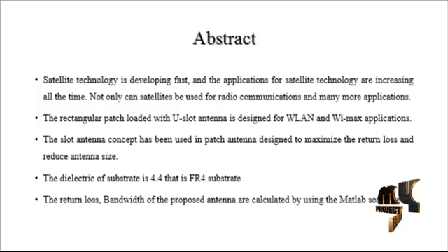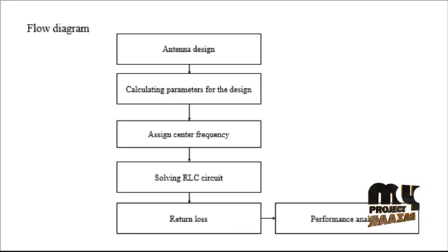CMA is carried out for critical parameters such as substrate electrical thickness, slot width, probe radius, and feed location variance to assess the dominant effects on the characteristics of the U-slot microstrip patch antenna.